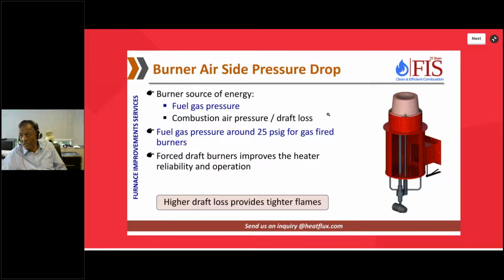Nobody talks about these. In fact, the burners never figure in radiant heat transfer calculations. That's the situation, that there are no parameters. And you will see, I think I will cover it, that all heaters are still designed based on 1940s Lobo-Evans correlations, so the number of burners or these things do not come into the picture.